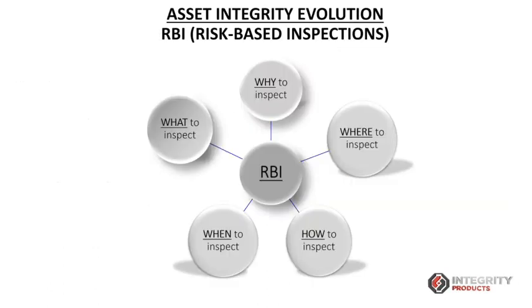I just introduced a second concept, which is RBI, risk-based inspection. We know what inspection is: we need to conduct ultrasonic thickness or radiography. Then what is risk-based inspection? What is the specific technique that we need to implement? RBI is simply a mindset that takes risk into consideration and helps us organize and strategize the inspection activities. We do the same radiography and the same ultrasonic thickness even with RBI, but in a more systematic and smart way, so we can focus on all the required inspections and only the required inspections.